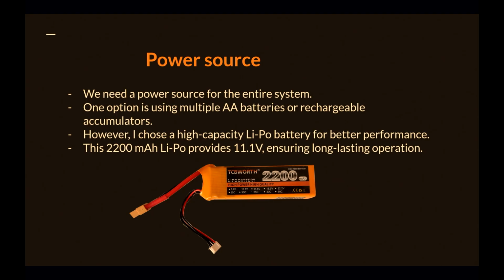But if you ever try to use that battery, don't connect it at the beginning of your development process. You need to check that you don't have shortcuts or other problems, because these batteries are really dangerous. If you shortcut it, it can cause a fire.